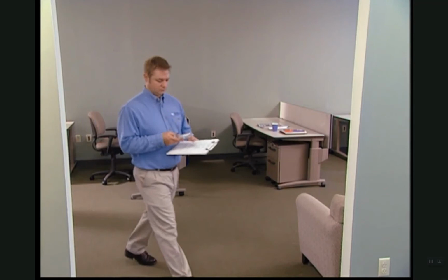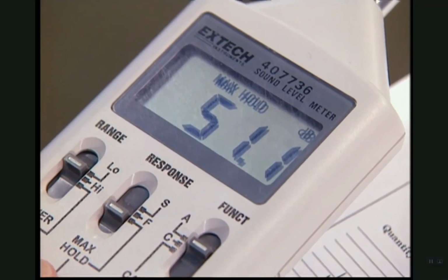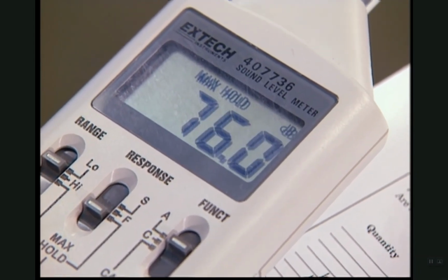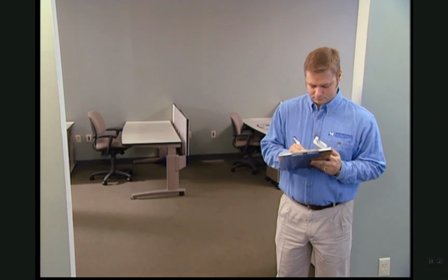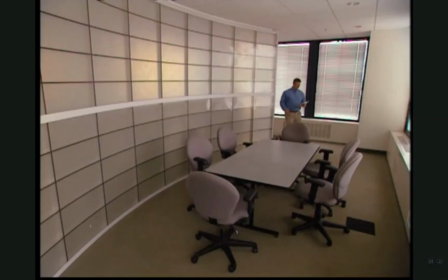Then you must actually measure the intensity of the sound. Measure the sound pressure level of audible appliances. With the appliance evacuation signal operating, take measurements at locations established during the acceptance test. Record the maximum output and compare the results with the acceptance test reading. Measure the sound pressure level of speakers and other voice messaging appliances in the same way, using the same meter.